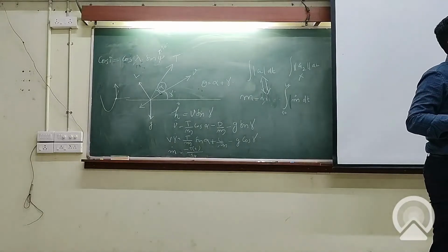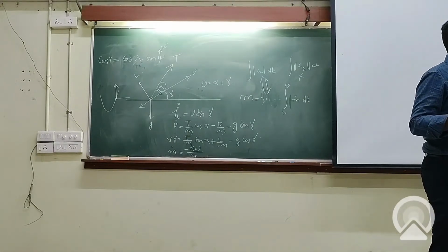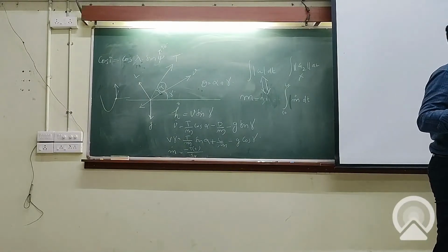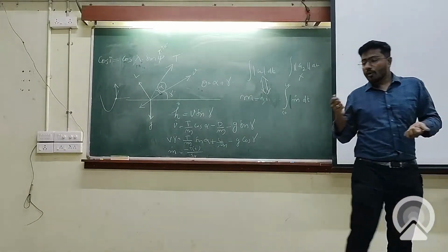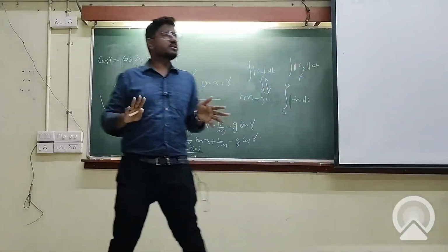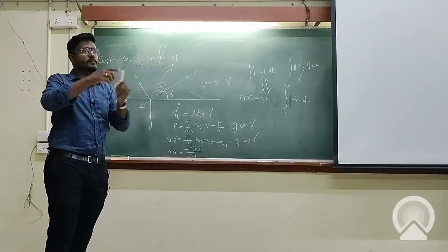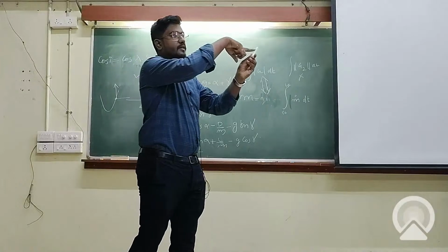So you have to design the structure as light as possible. Then whatever structural load may happen during the atmospheric phase has to be handled in the mission design. So what do we do? Basically, what are structural loads? They are lateral loads. You have the vehicle going up, and the aerodynamic forces are acting laterally.